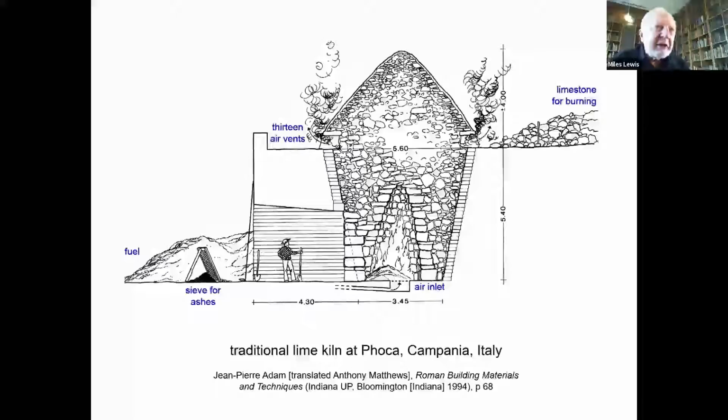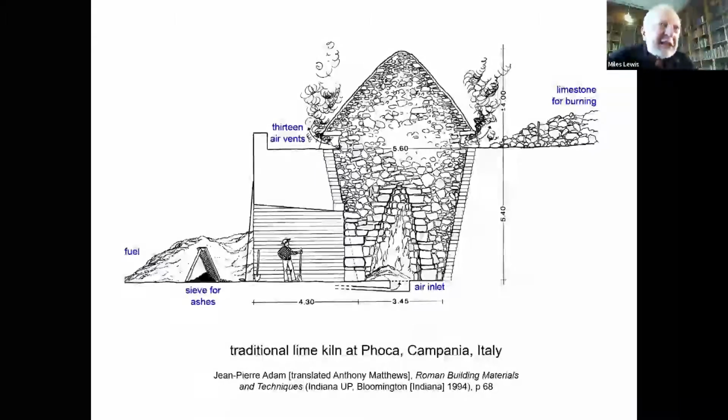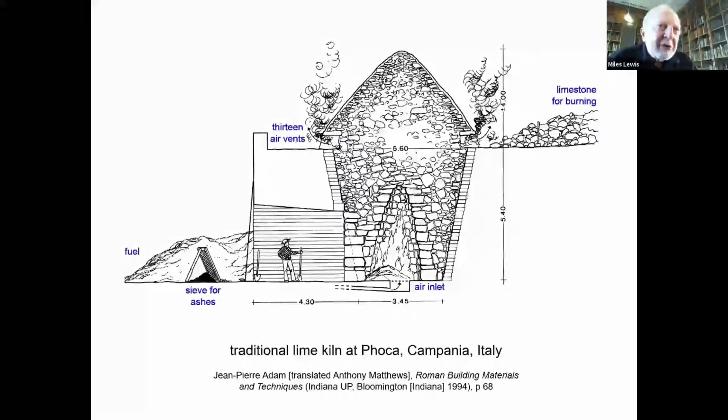So you have usually a conical sort of kiln, a kiln that slopes towards the bottom. And you build the limestone up inside it in a sort of temporary structure, leaving a space for the fire within. And you burn it for some time, maybe a couple of days before it's burnt through. And you then draw the lime off. So you tend the fire from the bottom, you actually put fuel in, and you draw the fuel off from the bottom as well. That's the basic sort of lime kiln.